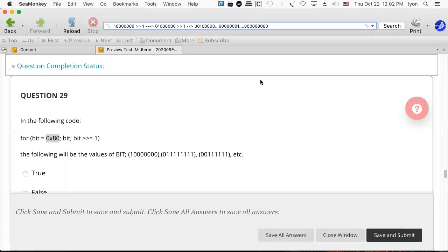And you can see from here, no, that's not what happens, right? Because it's just doing a shift off to the right, and the zeros are not wrapping around or turning to 1s or anything. So in effect, what this is doing is it's just taking 1 and shifting it. It's a shift register. And it's shifting the 1 until there's nothing left but 0.